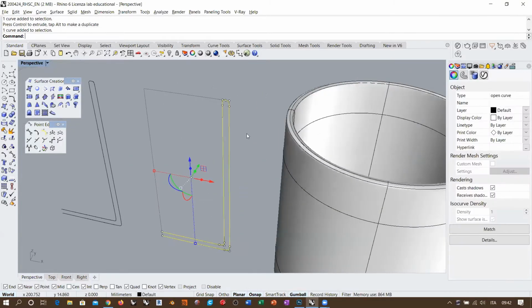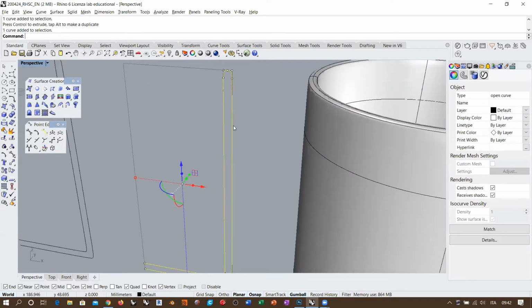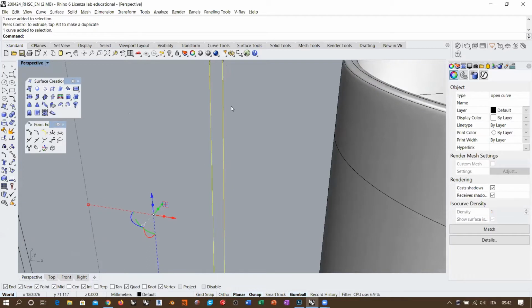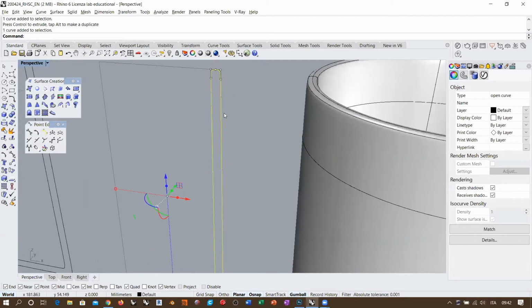And then take this one, and as I need to create a bulge, for example, here, and I don't have control points, what I need to do is to change the profile topology. Okay, so eventually I go here, I start adding, well, in this case, it's irrelevant if I add knots or control points, because the curve is so flat.